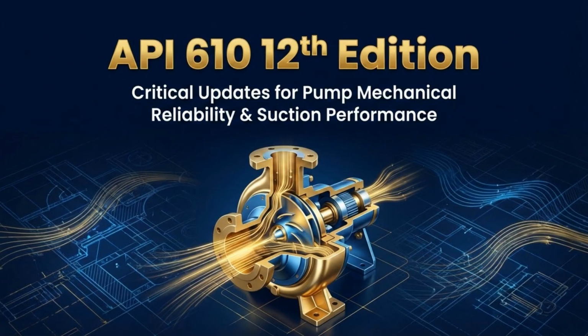The interesting thing is that most pump failures are not caused by hydraulic design, they are caused by things like vibration, seal failure, shaft deflection, mechanical instability. And that is exactly why standards like API 610 exist. API 610 is essentially the industry's attempt to capture decades of operational experience and translate that into design rules that make pumps more reliable. Today, we are going to explore the 12th edition of API 610 and more importantly, understand why the standard evolved the way it did.